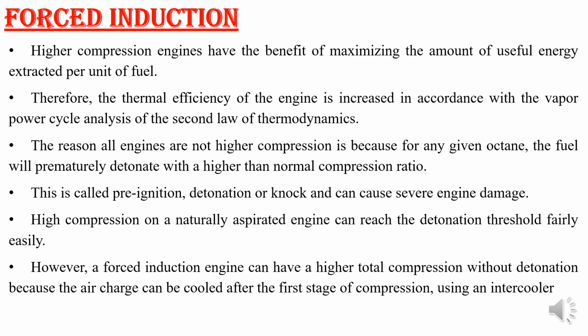So we get better combustion, meaning completion of hydrocarbon fuel, and CO emission formation might be lesser, but the problem is NOx emission, that is oxides of nitrogen. The formation of these oxides of nitrogen mainly depends upon the temperature and the oxygen content. Now we are providing more oxygen to the engine. What will happen? Then the formation of NOx also will become more.